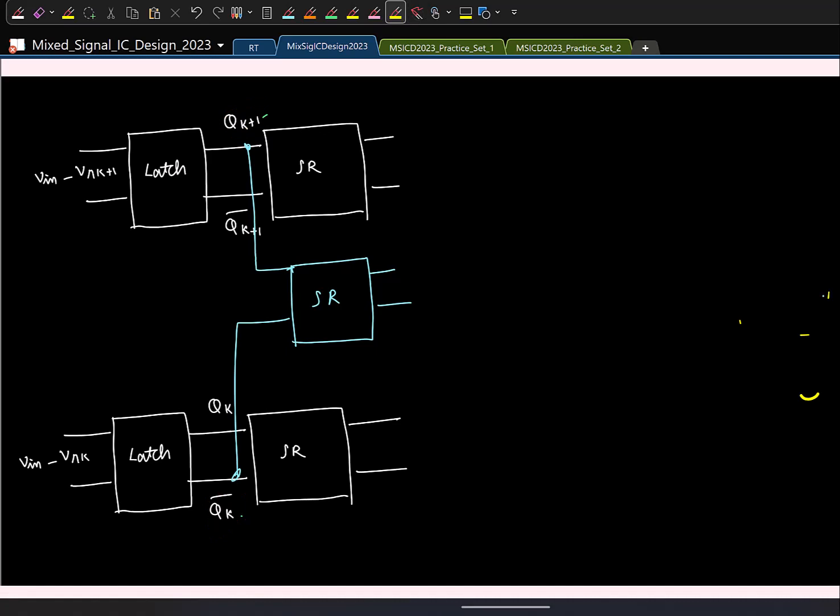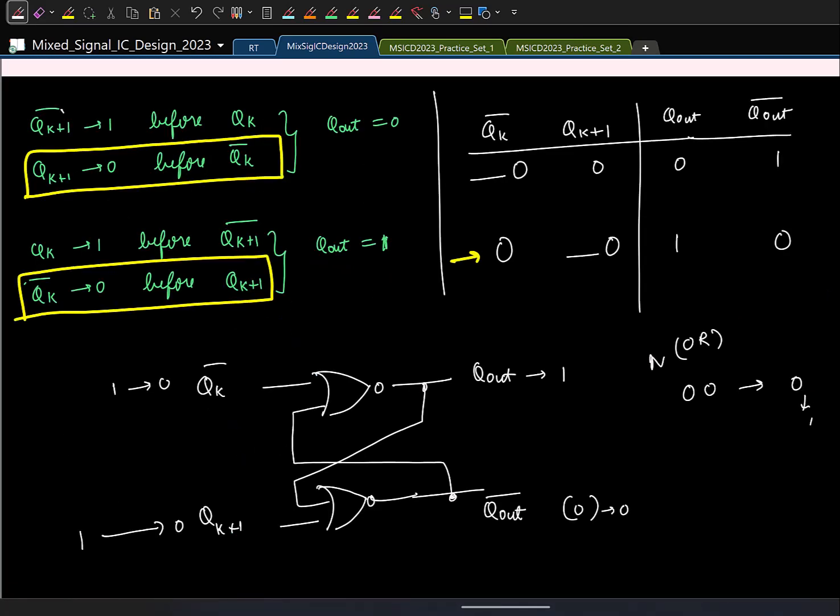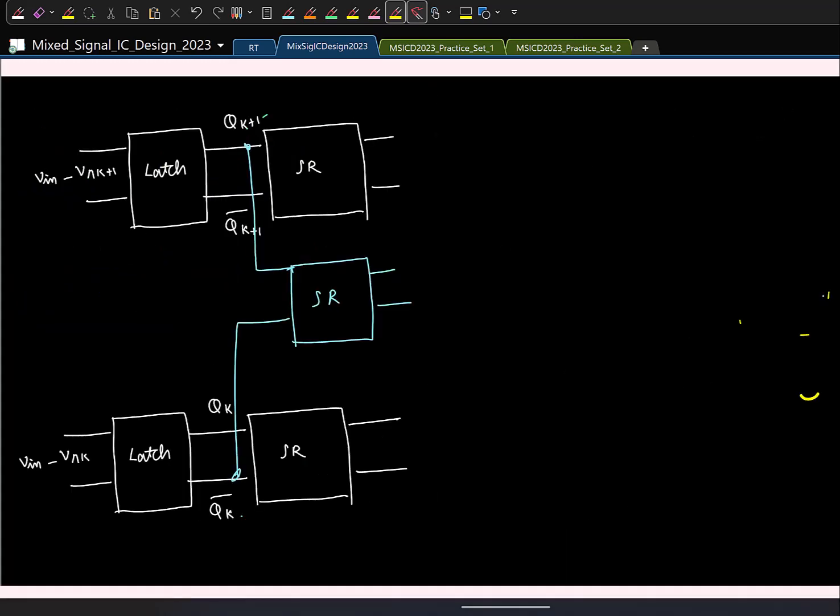Okay. So here if you see, we are doing interpolation, but we are not actually using the information in voltage, right? In the earlier case, we were doing interpolation in voltages, but here in which format is the information available? Yeah, digital, but we are basically checking which signal is coming earlier in time than the other signal. So the information is basically available in time. We are exploiting the time delay in the two signals. So this is called time-based interpolation.